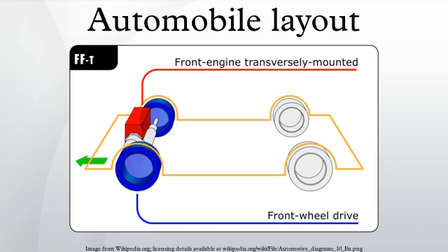Advantages. Interior space. Since the powertrain is a single unit contained in the engine compartment of the vehicle, there is no need to devote interior space for a drive shaft tunnel or rear differential, increasing the volume available for passengers and cargo. Instead, the tunnel may be used to route the exhaust system pipes. Weight. Fewer components usually means lower weight. Improved fuel efficiency due to less weight. Cost. Fewer material components and less installation complexity overall.